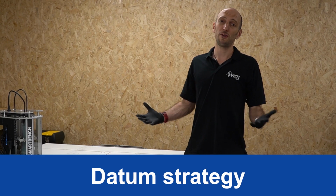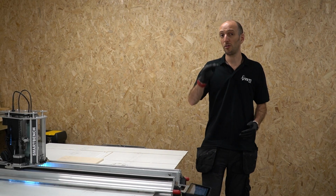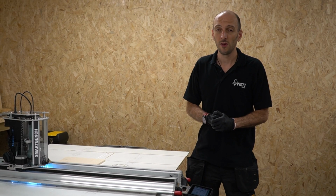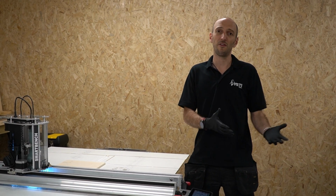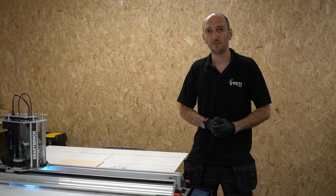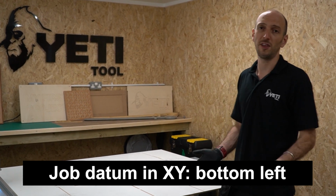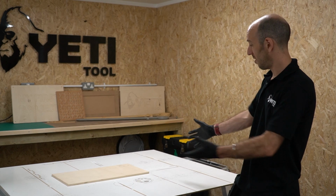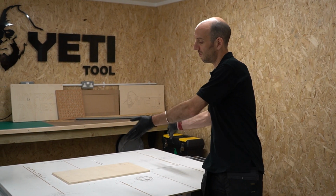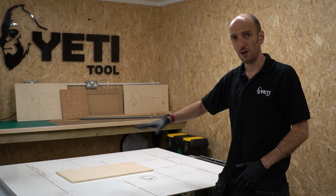Now, in the example we've just been through, we put the job file's datum in the bottom left corner and on the top surface. But that's not the only place we could have put that datum. So let's just have a look at some of the different options that we've got available to us and some of those pros and cons. The bottom left corner that we used is actually a very common datum point, and it's useful because it's close to our home position, but also that we can get a good visual representation as to what the total footprint of the job file will be.